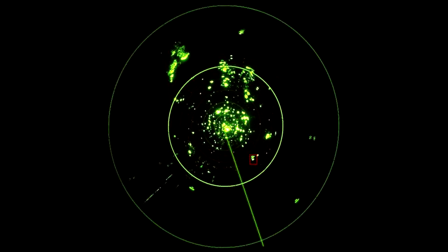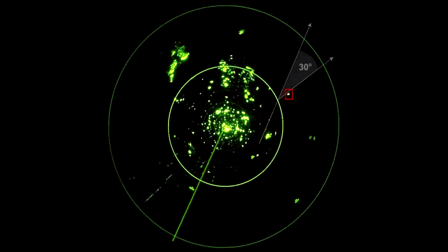The final method is by ascertaining the aircraft heading, if circumstances require, and following a period of track observation, instructing the pilot to execute one or more changes of heading of 30 degrees or more, and correlating these movements to a radar target. A controller may request that a possible radar contact repeat manoeuvres as many times as necessary to confirm aircraft identity.